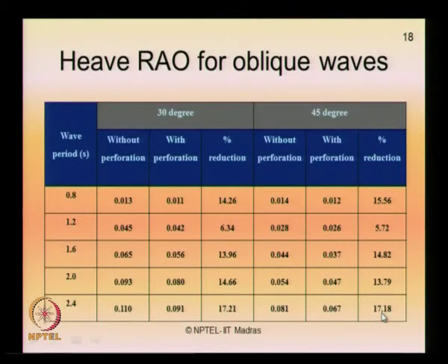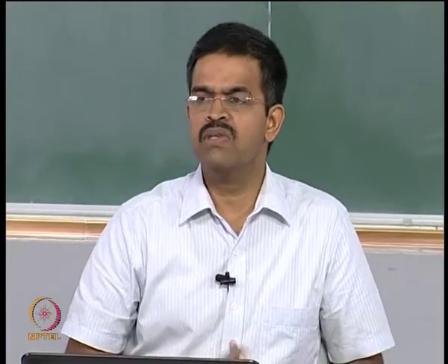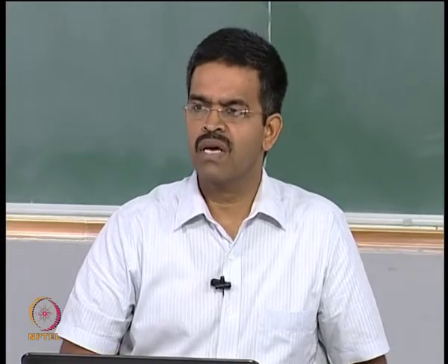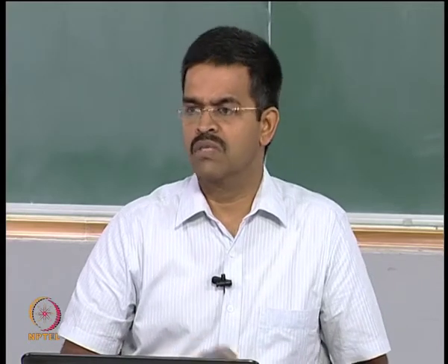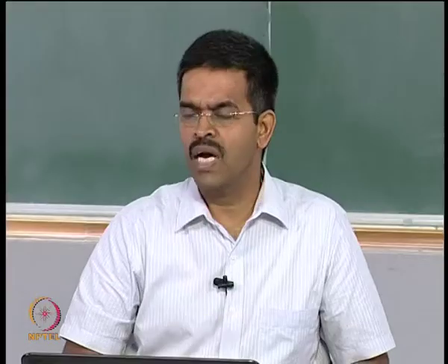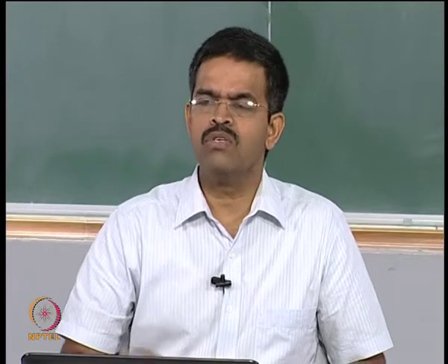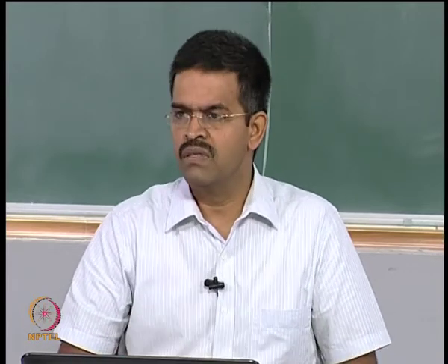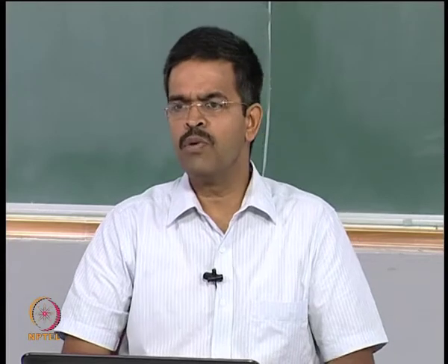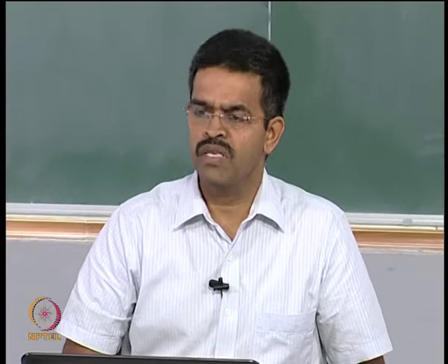So, it is understood that there is a significant percentage reduction in surge and heave responses on the inner members when they are covered by perforated outer covers. There is a reduction in tether tension variation when you cover the members using a perforated outer cover. We have understood that there is a reduction in the response which can be connected to an increase in damping coefficient in surge response, because the moment you put an outer perforated cover, the damping coefficient in surge degree also varies significantly.